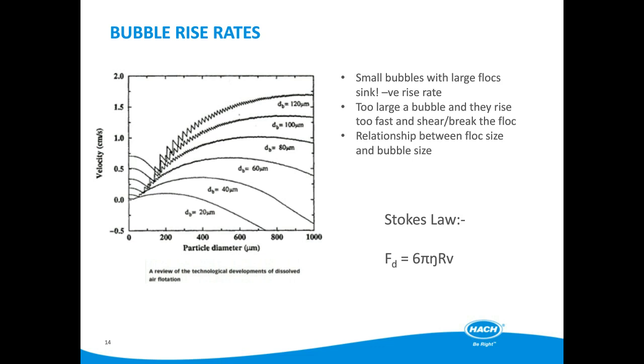As mentioned, the rapid pressure release on the recycled water causes the production of microbubbles. However, the recycled water may also act similarly to a fizzy drink, in that there will not be an instantaneous, complete desaturation of the water. If this were to happen, then fizzy drinks would not really exist. If we think of a glass of carbonated water again, bubbles still continue to rise from fixed points in the inner surface of the glass.